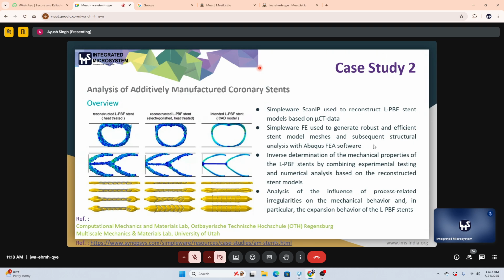So once we are doing the 3D printing, we aren't that sure whether the particular printed part would last for a significant amount of time. So we need to do an analysis of the same. We need to do bench testing of the particular product, to see whether it will take any wear and tear over a period of time. Every product does wear and tear over a period of time, but we need to take the time into consideration, because if wear and tear is occurring after 20, 30 years, then it's of no issue, because that's the specific lifespan for any implant part that is being inserted. So coming back to the point.